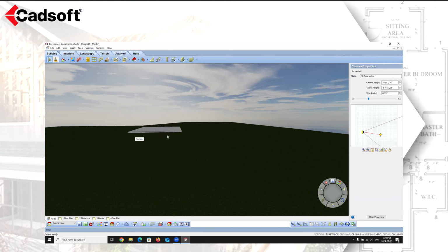The rest of this would be filled in with gravel or whatever I need. So I just want the actual true calculation of what a 4-inch thick slab would be. So that would be the more accurate way for estimates. If it's just to be something that's going to be shown as a rendering or a 3D view to show a client, then the pad option will work just as well.